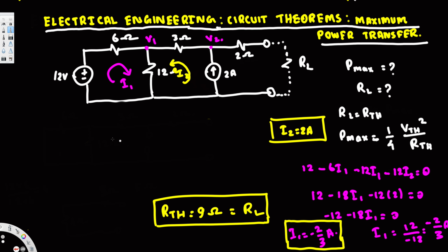Okay, here we have 12 voltage, right? And if we subtract this voltage from this one, that's going to give us V1. And here, since this is going along current direction, we have to subtract that one definitely. And this is going to be 6I1. The voltage is going to be, because V is equal to IR, right? V is equal to IR, 6I1.